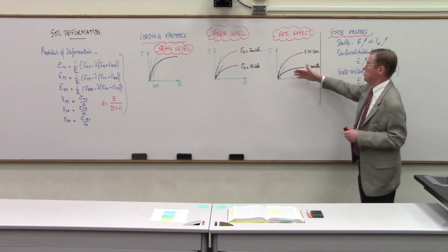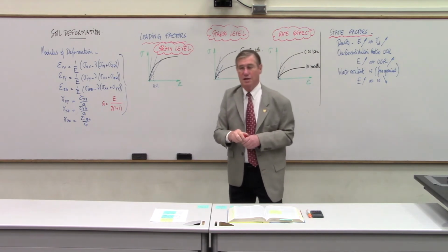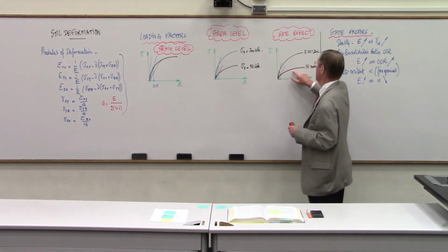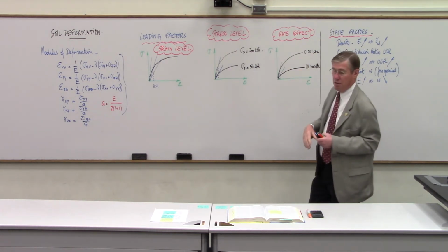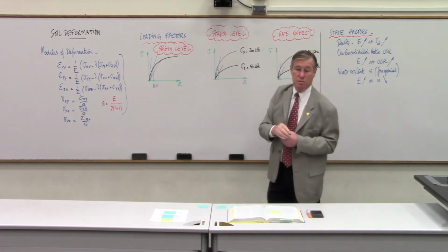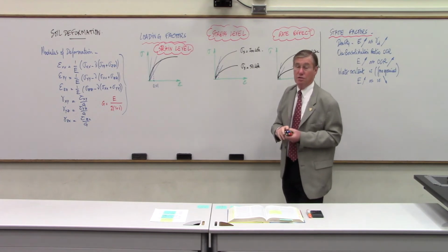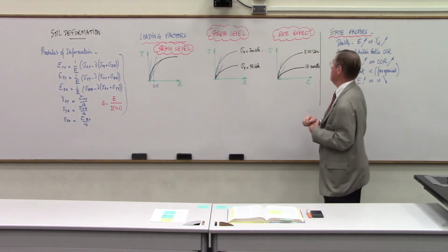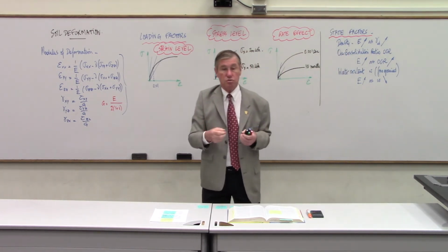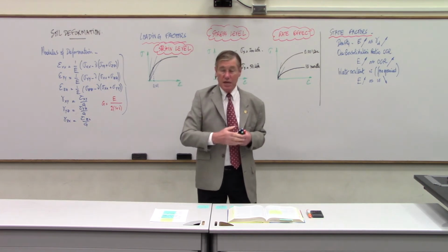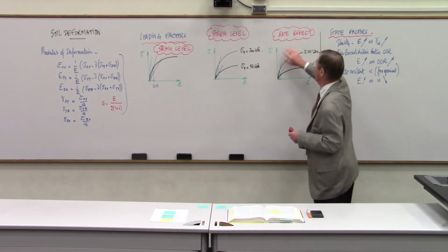10 months, when we do calculations of settlement, Tower of Pisa, been around 900 years. Well, that's a long-term modulus that we would need to predict the behavior. But if we are doing the pavement loading, for example, a car traveling at 100 kilometers an hour, that's not going to stay on the load, apply the load for very long. Or if you lose control of your car and you hit the guardrail on the side, the post is going to be pushed in a few milliseconds. So now the rate of loading has an impact.